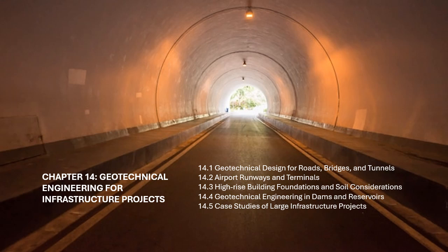14.4.4 Monitoring and maintenance of dams and reservoirs. Geotechnical engineers play a vital role in the ongoing monitoring and maintenance of dams and reservoirs. Regular inspection and testing are necessary to ensure the continued stability of the dam and to detect early signs of potential failure. Monitoring includes piezometers. These instruments measure the water pressure within the soil or rock beneath the dam, providing valuable data about changes in the groundwater conditions and potential seepage.